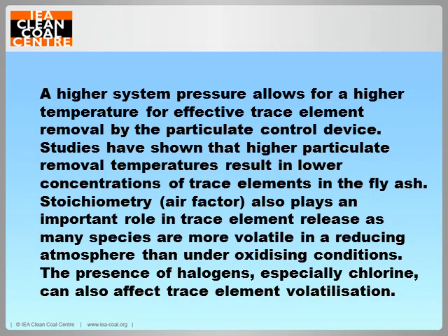Stoichiometry, or the air factor, also plays an important role in trace element release, as many species are more volatile in a reducing atmosphere than under oxidizing conditions. One kilogram of coal will typically require 7 to 8 kilograms of air, depending upon the carbon, hydrogen, nitrogen, oxygen, and sulfur content for complete combustion. This air is also known as the theoretical or stoichiometric air.